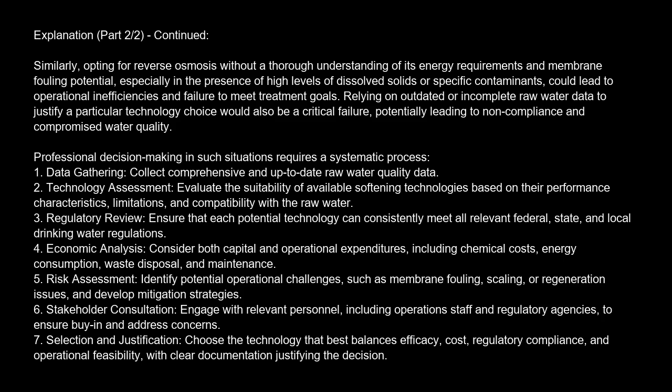Professional decision-making in such situations requires a systematic process. 1. Data gathering. Collect comprehensive and up-to-date raw water quality data. 2. Technology assessment. Evaluate the suitability of available softening technologies based on their performance characteristics, limitations, and compatibility with the raw water. 3. Regulatory review.